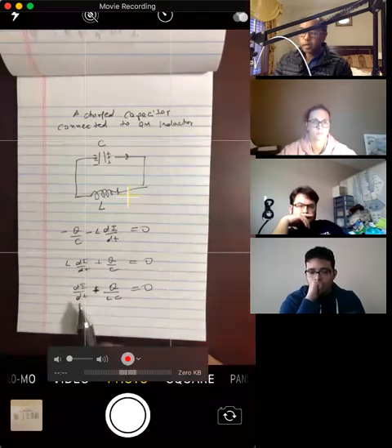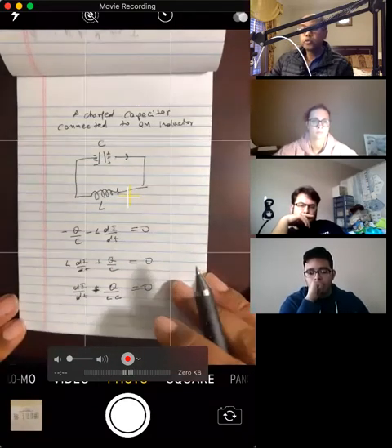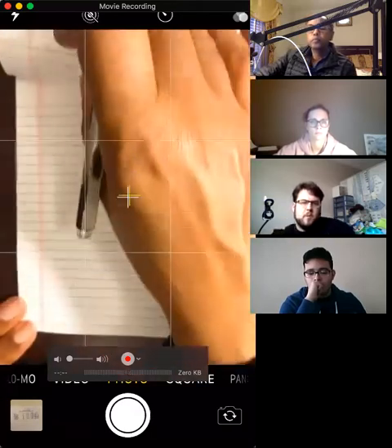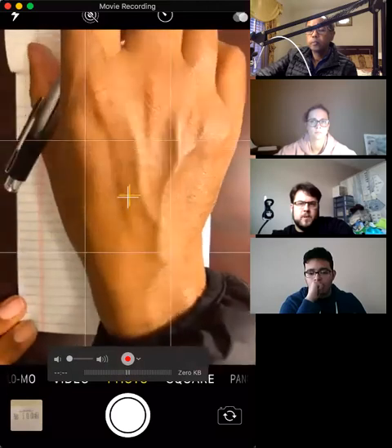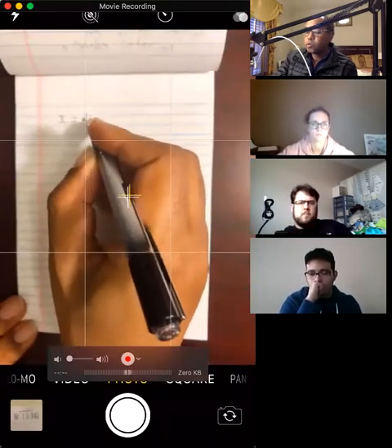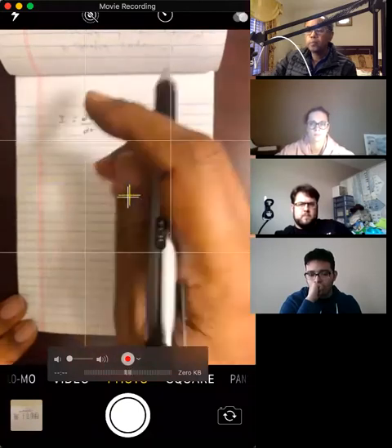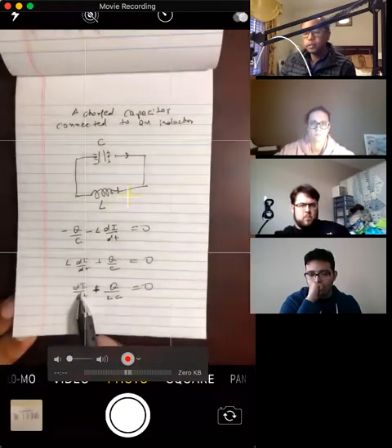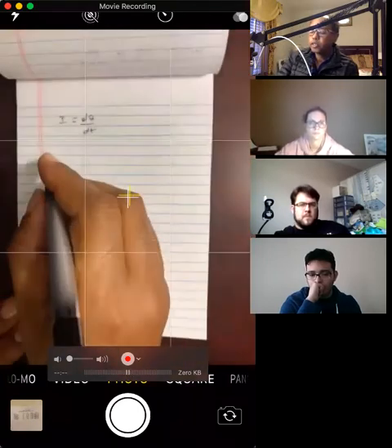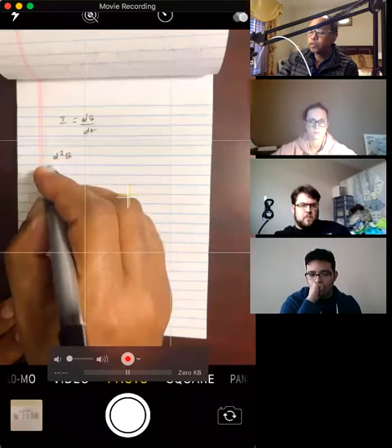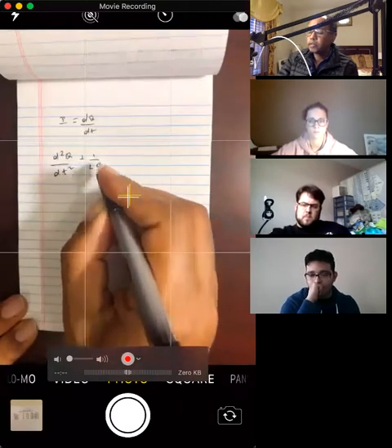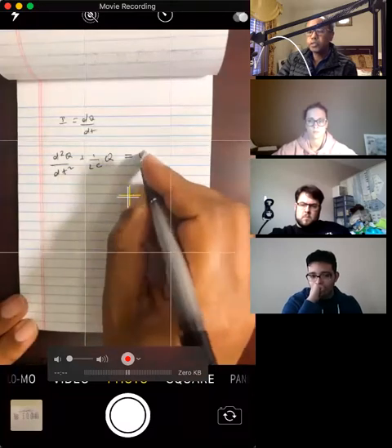But we have I and Q. How does current relate to charge? It's the derivative of charge: I is dq by dt. So we have the second derivative of q with respect to time plus 1 over LC times Q equals 0.